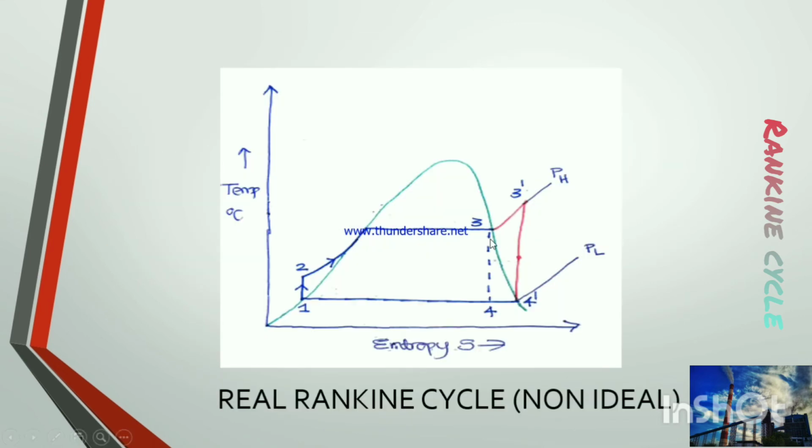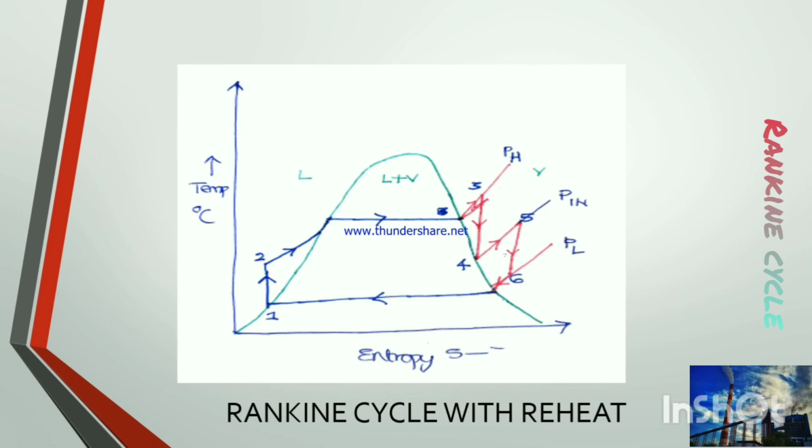That is, the working fluid is heated to a superheated temperature, and the superheated working fluid is then supplied to turbine where it undergoes isentropic expansion process. During this expansion process, water droplets are not formed, so pitting and erosion are avoided. Then Rankine cycle with the reheat.